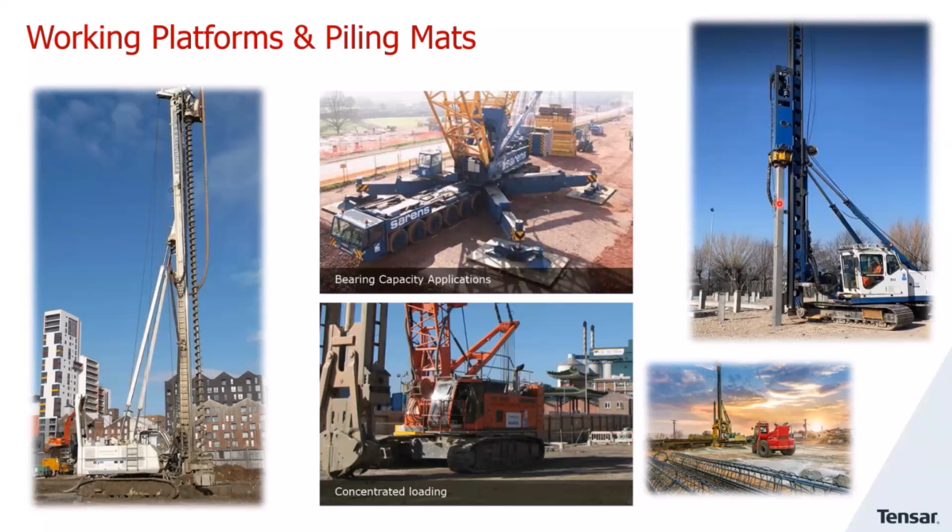Piling mats are working platforms designed specifically to carry the heavy static and dynamic loads from piling rigs, their support cranes and associated equipment. Often placed over weaker subgrades, temporary working platforms are typically built using well-graded, compacted granular fills, such as natural gravels and crushed rock, as well as recycled demolition material. Tensar geogrids can be used in the granular material to stabilize it and thus increase the bearing capacity.